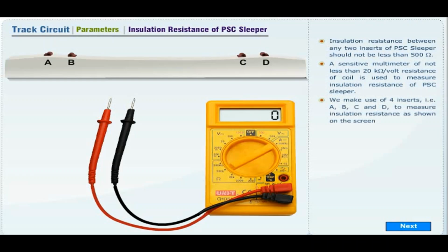Insulation resistance of PSC sleeper. Insulation resistance between any two inserts of PSC sleeper should not be less than 500 ohms.